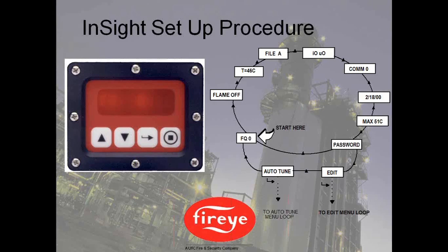The next item in that outer layer menu is whether your flame relay is on or off. Some people will leave it there so they know if it's seen the flame or not. Temperature is available in Fahrenheit or centigrade, and then there are 4 files to select from, and that will tell you which file you've selected. You also are able to see that pulse count that I referred to earlier in the flame quality, and that is the raw count of flicker that it is seeing.